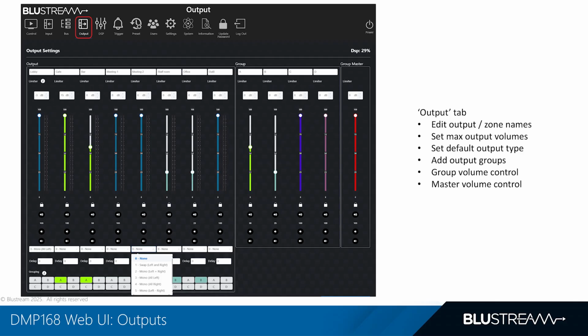And with mono summing, it'll take stereo content and combine it into a single channel, perfect for paging systems, single zone rooms, where of course stereo may not be practical. And one last detail, this is also where you'll find the lip sync delay adjustment available per output or channel. And that means you can ensure dialogue matches the video on screen zone by zone.